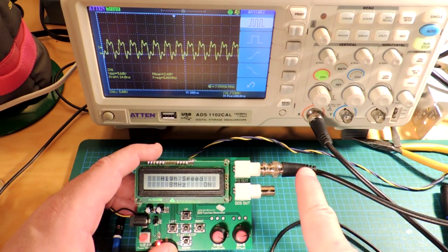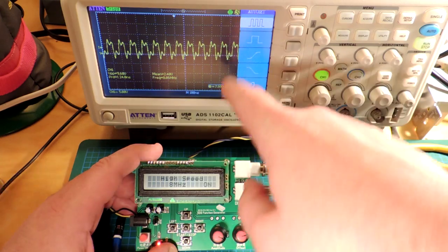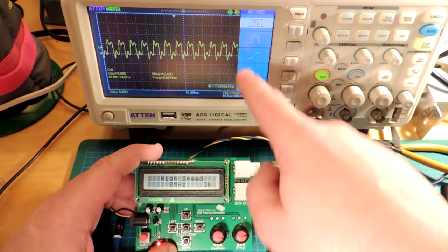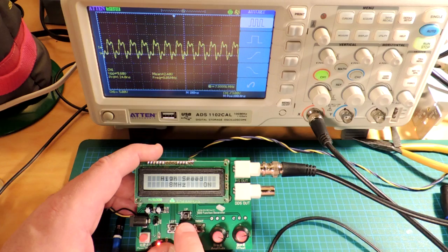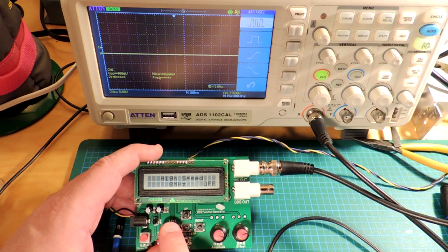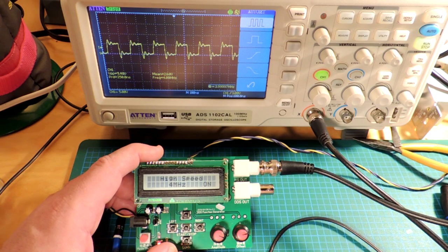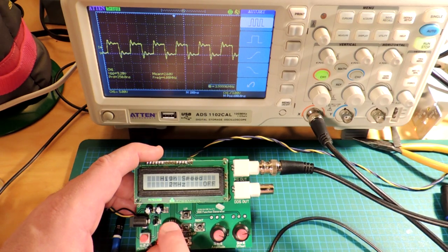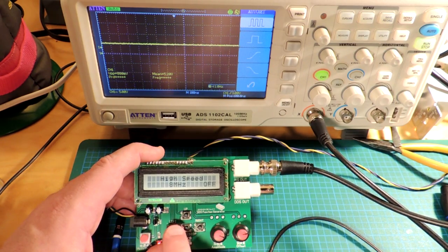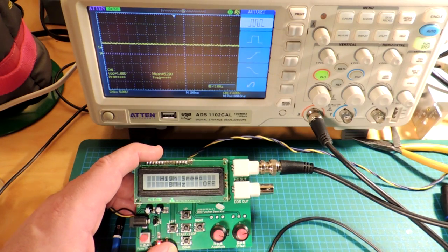So the second output is what they call the high-speed output. You can see there's an 8 MHz on the display here, and an 8 MHz square wave. Just like the other direct digital synthesis mode, you actually have to stop the generator before you can change it to another frequency. It's kind of a curious selection of frequencies. It's just a binary stepping of 1, 2, 4, or 8 megahertz. So I guess useful if you want a sort of moderate speed clock into some digital circuitry you might be prototyping.